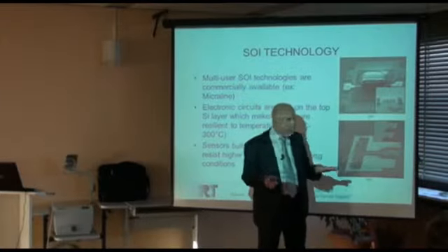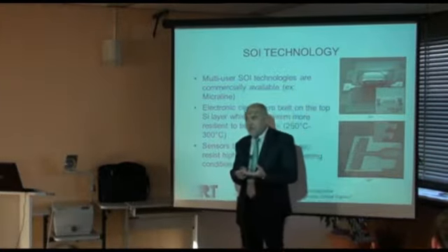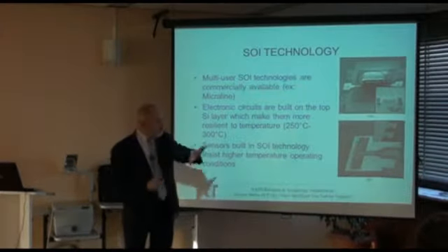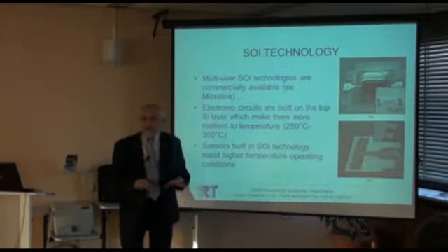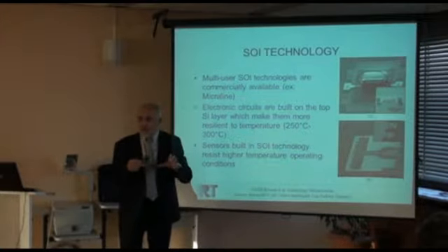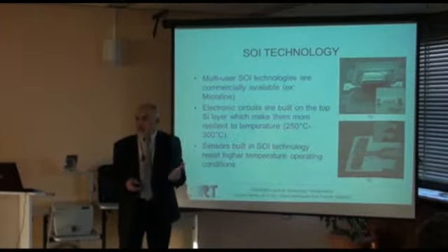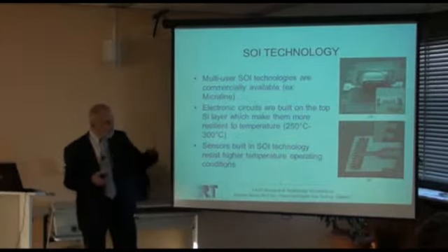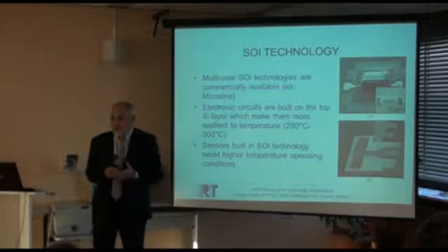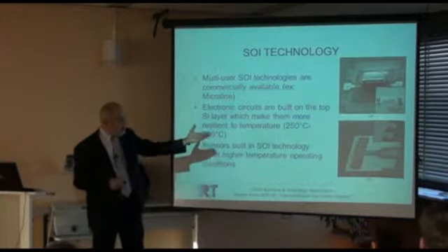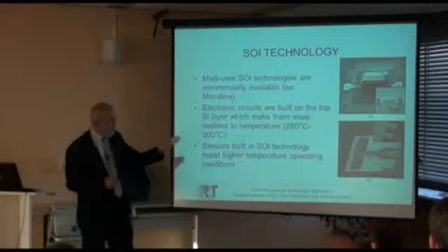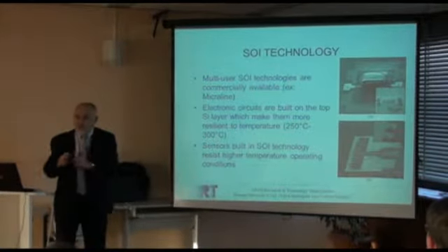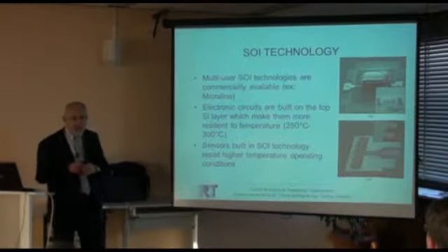It's extremely important they are not touched by hand because the force induced by hand is not controlled. But the flow will just push them down. Now, if there is a separation of air, there will be turbulence, and these beams will start shaking, and eventually the shaking could be detected. So they are good candidates for that type of technology. They could be built in silicon. This is silicon on insulator, so they could easily take 150 degrees even with the electronics attached.